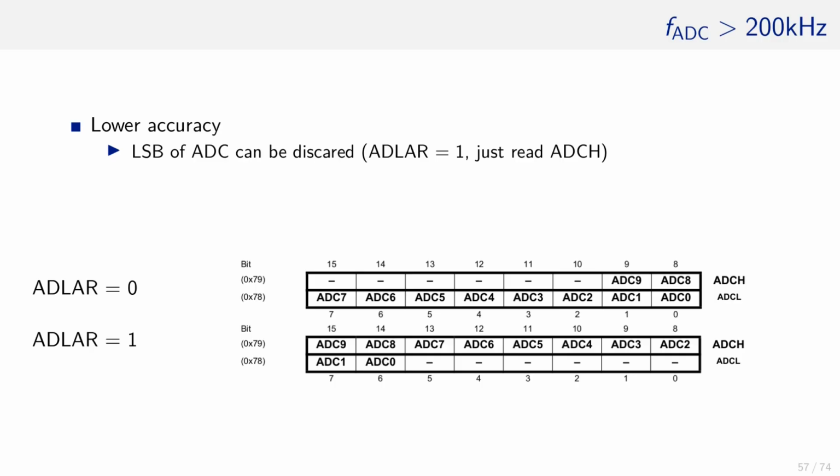Imagine you ask the ADC to sample an analog voltage level, give it some time, and it returns the 10-bit value after that time. Now you're in a hurry and you do not want to give the ADC that much time anymore. So the ADC is stressed and most probably will get the last 2 bits wrong. They are the tricky ones anyway, since they influence the measurement by just a little bit, as we have seen in the examples earlier.